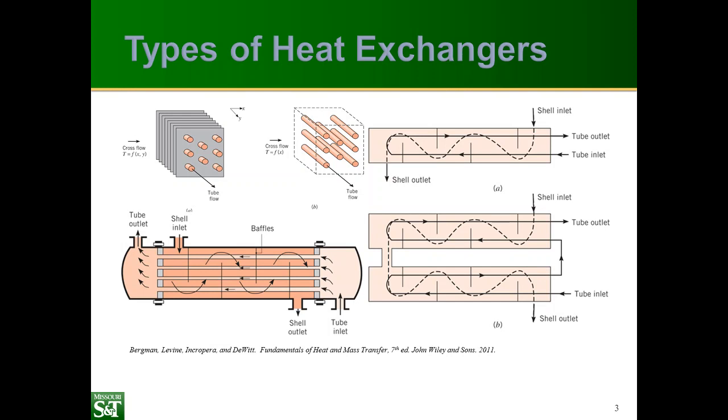If you need additional performance, you can attach these heat exchangers in series to one another, so you have multiple shell and tube heat exchangers. But the problem here is that each additional shell has essentially a reduced return on investment. So you need to balance the construction cost and maintenance cost against the improved performance of the heat exchanger.